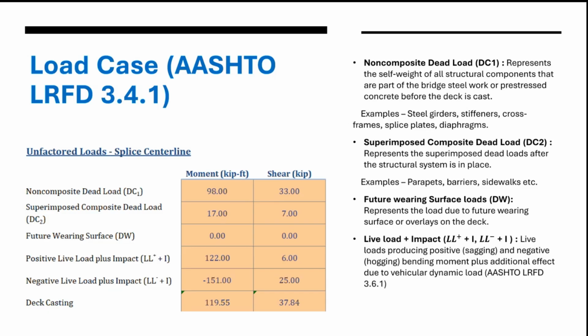Yeah, it depends. If you follow AISC purely, they don't require achieving the full capacity. We don't need to achieve the full capacity from the splice plates, but AASHTO requires you to achieve the full capacity of the member for the splices. And if you're doing buildings versus roadways, your stipulations change. But we do it for the full capacity.